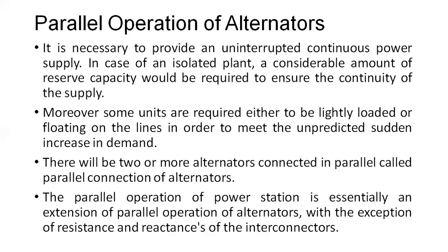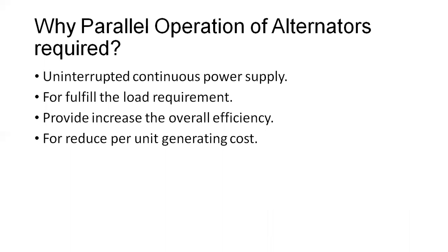It is a very important part, and the condition is that the resistance and reactances of the interconnectors should be matched with both alternators. So why are the parallel operations of alternators required? Means what is the reason of parallel operation? Already explained. That is, first of all, uninterrupted continuous power supply.